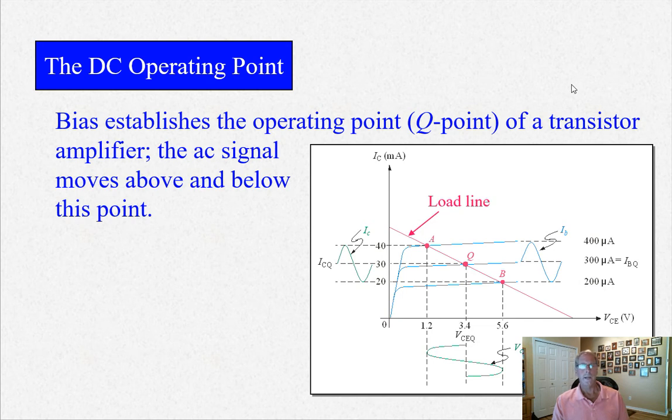Hello everyone. Today we're going to talk about biasing a transistor. Basically, we need to put the base junction at a spot where when you apply a small voltage to the base, it produces a base current, which in turn turns on and off the transistor, which reduces the collector emitter effective resistance and therefore controls that current.